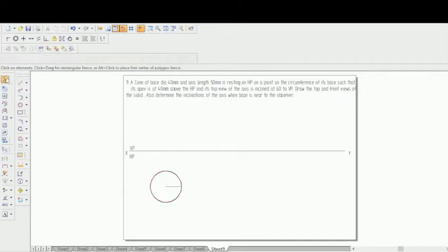Now we'll have to draw a pattern. Select this line, go to circular pattern. Give the number of counts as 8 and the angle as 360 degrees, because we are going to make 8 divisions for the entire 360 degree circumference of the circle. After giving 360 degrees, press enter, and after clicking at the midpoint of the circle, click finish.